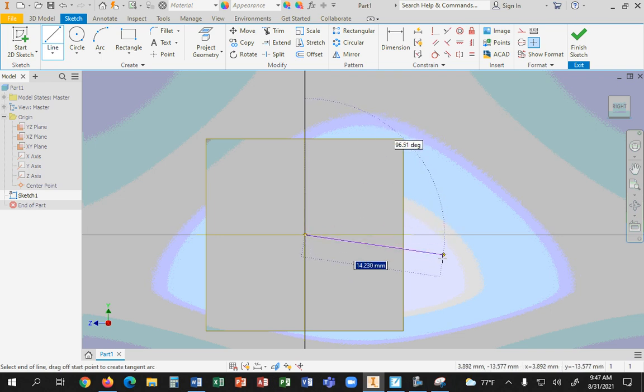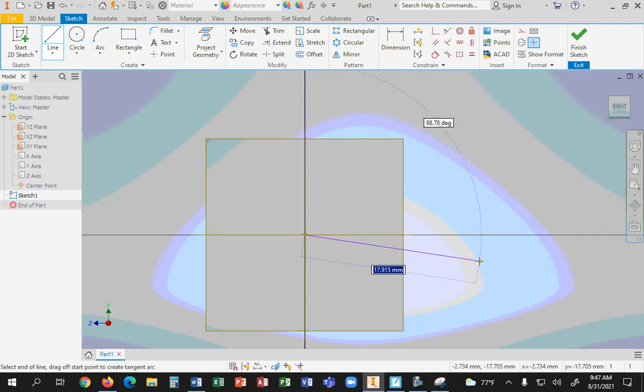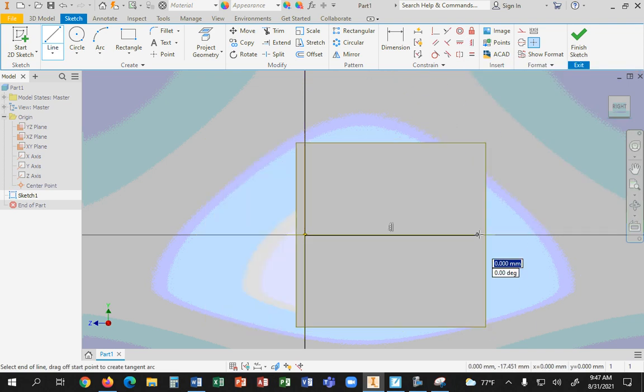If you don't see a green line when you draw, or a green reference of any kind, see when I go across, see another constraint. Look on the right side of this image. You see another little constraint. You're like, what does that one mean? Go up here and it tells you vertical constraint. Don't worry about it being a horizontal line. I know it sounds confusing. Ignore that. On the constraint, just ignore that and just keep working.